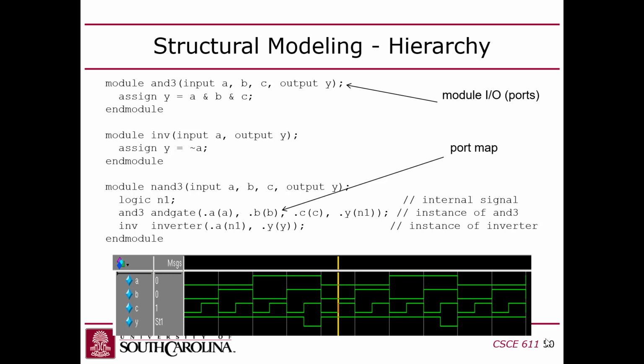If you notice, A, B, and C are square waves, but the period of A is twice that of B, and B is twice that of C. So if you look at any moment in time, you get a counting sequence. This is 0, 0, 0 for A, B, and C, and then 0, 0, 1, where C is 1. If you look at A, B, and C as a number, where A is the most significant bit and C is the least significant bit, then it's just counting from 0 to 7.